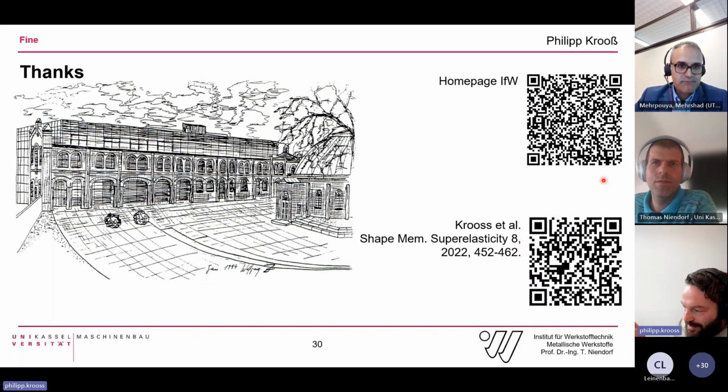It's a technique where you need to look at the orientation, on which plane the precipitates form, and then you do diffraction, and you can prove that there is the presence of precipitates in this particular plane. There are books of like 1,000 pages where you can look up the planes you need to look at in different crystallographic structures, and then you can prove the precipitates are present or not. So TEM is the method you should use here.